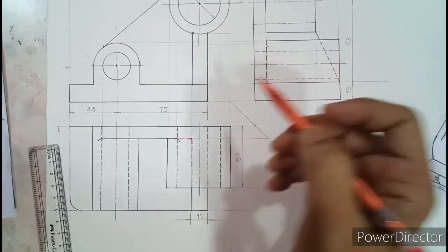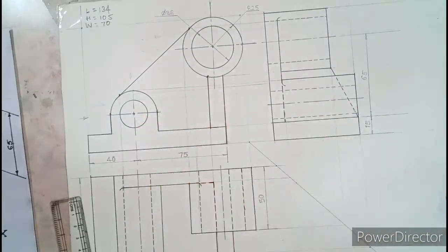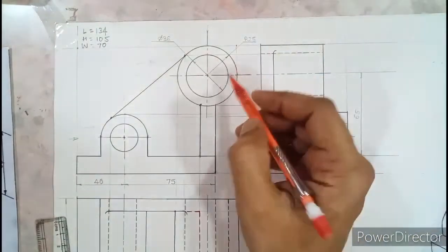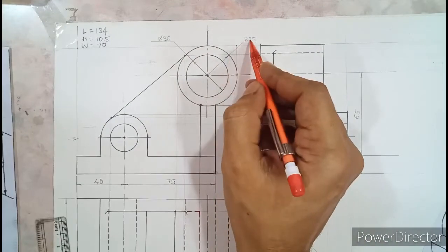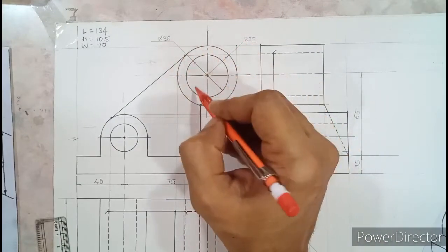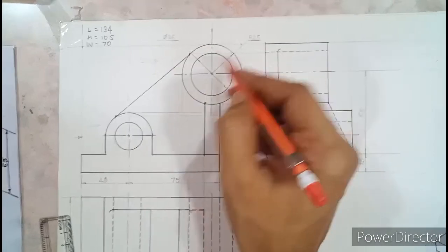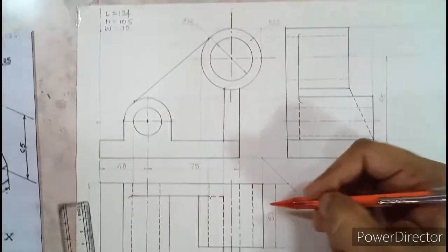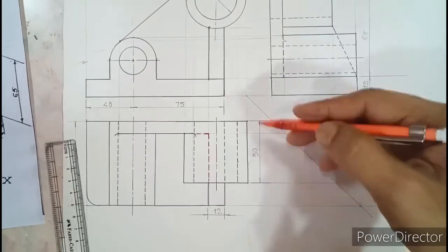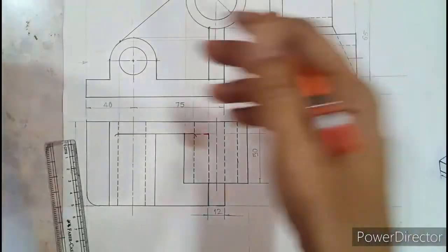Now see, there is no point in showing circular dimension because the examiner just wanted to know, are you aware of circular dimension, and you have already shown here R25 and dia 36. So the examiner has understood that you know how to show circular dimension. There is no need to show it again here. Instead, if you show linear, you can complete your task quickly. So we have shown 9 dimensions.